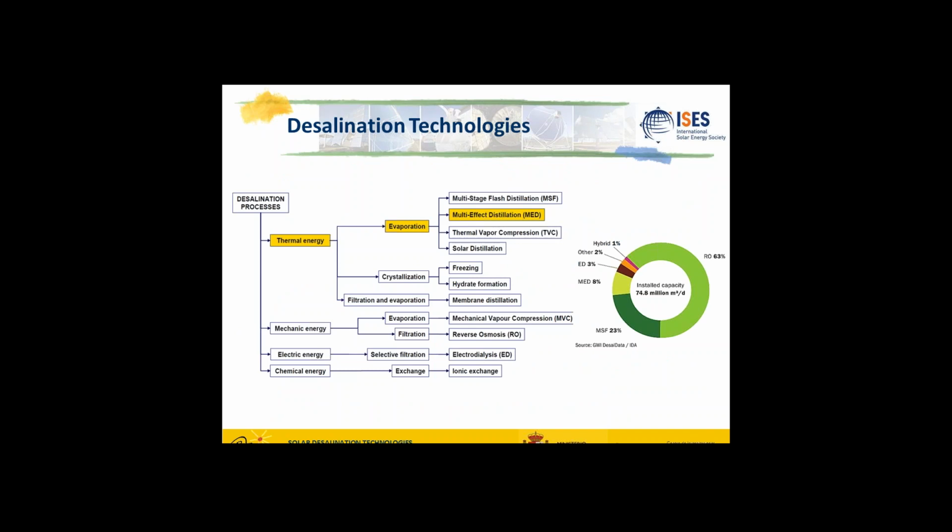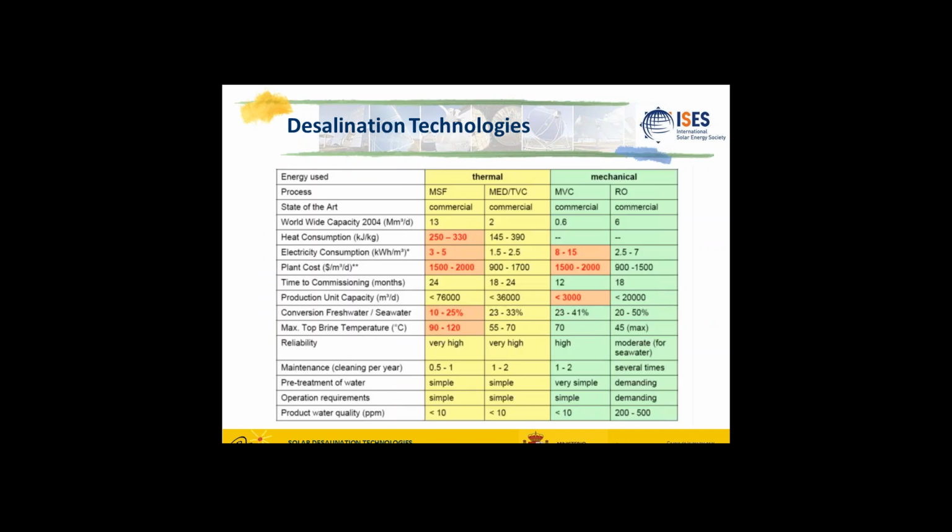For example, you see in a typical fossil power plant the temperature-entropy diagram when you work, for example, at 530 degrees Celsius, you have this typical cycle. But in a parabolic trough solar plant, the top temperature today is typically 400 degrees Celsius, so you have this cycle here. If you compare, that means that the cooling requirements are more or less the same, but obviously, in the case of the fossil fuel plant, the electricity produced is more. So that means that we are going to consume more cubic meters in the case of a water-cooled plant per megawatt hour of electricity produced.